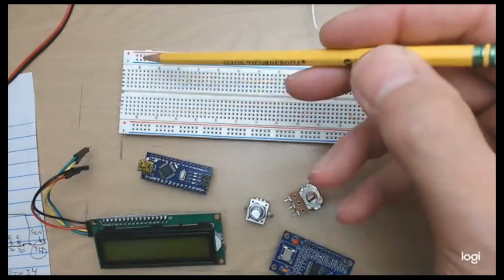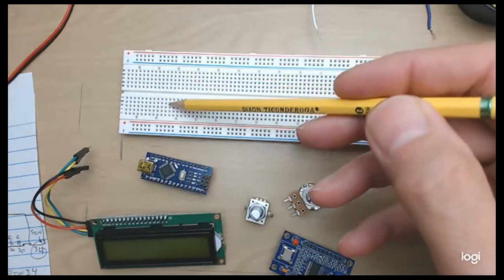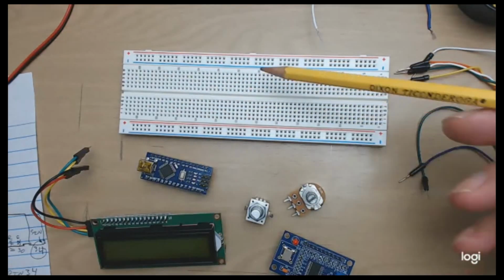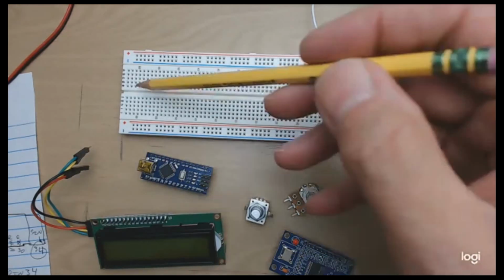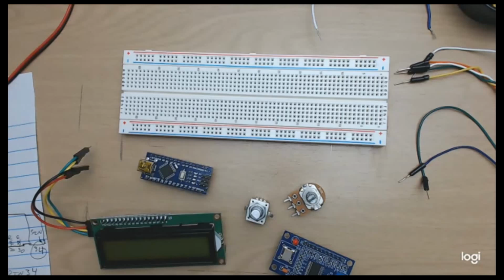So that's first thing, the breadboard. And then each one of these, what will look like vertical stripes, or vertical rows of pins are connected to each other. So you can use each one of these, and it's just like a solder joint. This middle row is a division, so the things on the top and the bottom are not connected to each other. So that's a little bit how a breadboard works, and you can build all kinds of circuits on a breadboard. You can build little amplifiers and all kinds of things. Tonight we're going to build the signal generator on there, and we're going to demonstrate how that works.